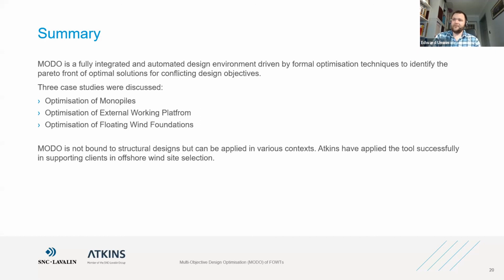Yeah, go on then, Hieu. Sorry, I just say I think I've seen a concept where they have the vessels and then the turbine with the spar and the turbine already installed, but there will be other issues with that in terms of how high the hub height should be, and whether there will be wave impacts on the blade and other stuff. So either way, you face some issues. If you don't have the turbine already attached to the spar, then you have a problem installing it on site. And if you have it attached, then you have to deal with the wave impacts when being transported.